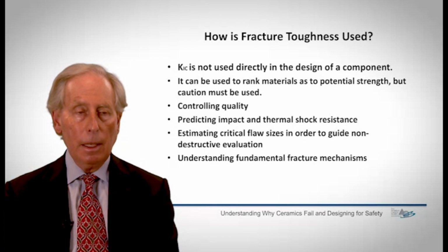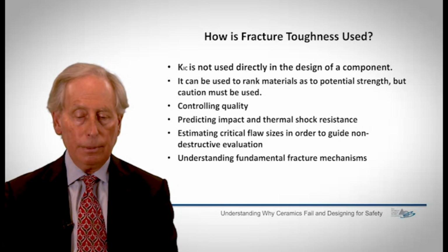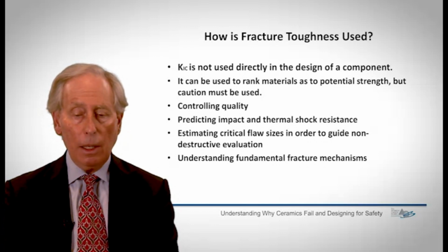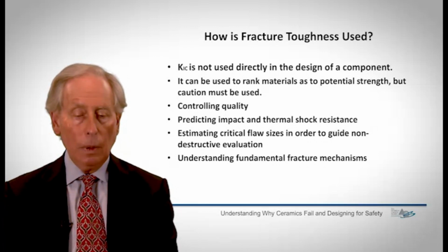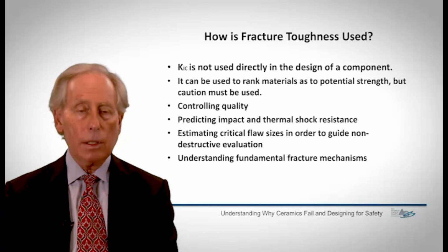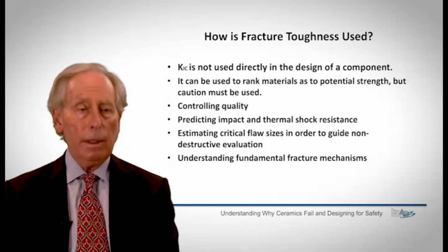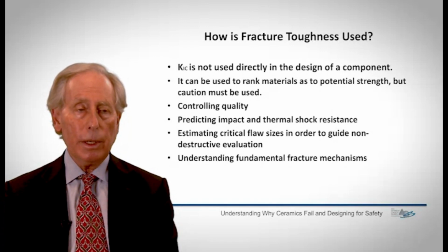So it's a guide to the non-destructive evaluation of, if you will, what should I be looking for in terms of flaw sizes. And it can be used to understand the fundamental nature of fracture. And we talk a lot about that when we talk about slow crack growth. So again, reiterating, I'll show you that in the end we won't use fracture toughness very much in terms of predicting strength, but it really helps us to understand what's going on in the material, what might be going on at the crack tip, choosing a material, looking at microstructural effects, and so forth.